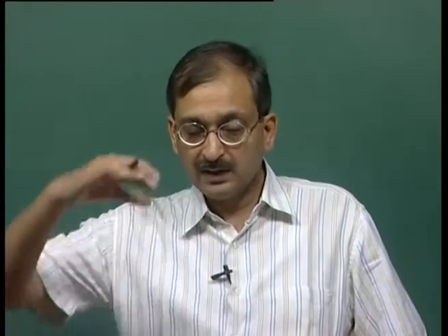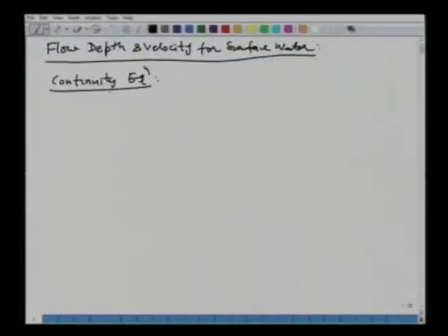What are the inputs and outputs? Well, the rainfall is falling from the top, there is infiltration taking place, and there is overland flow, where the flow depth is y and the velocity is v. Our objective is to find this v and y at the end of this control volume. Then we first write the continuity equation and state conditions. The Reynolds transport theorem for the mass comes out as: integral of beta rho v dot dA equals 0. Beta is 1, rho will come out, so you have v dot dA equal to 0. This is equation 5.61.